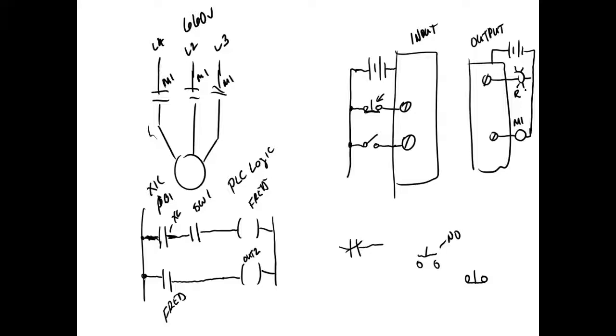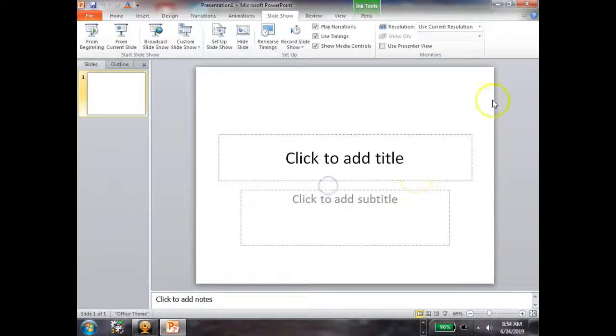But what you got to understand is that the way the author drew this, light bulbs don't control contacts. Right? Light bulbs just light up. But this author assigned a contact to a light bulb. So change that R to a relay? Yeah, just change it to a relay. And then when you draw your outputs, right? Everybody okay?